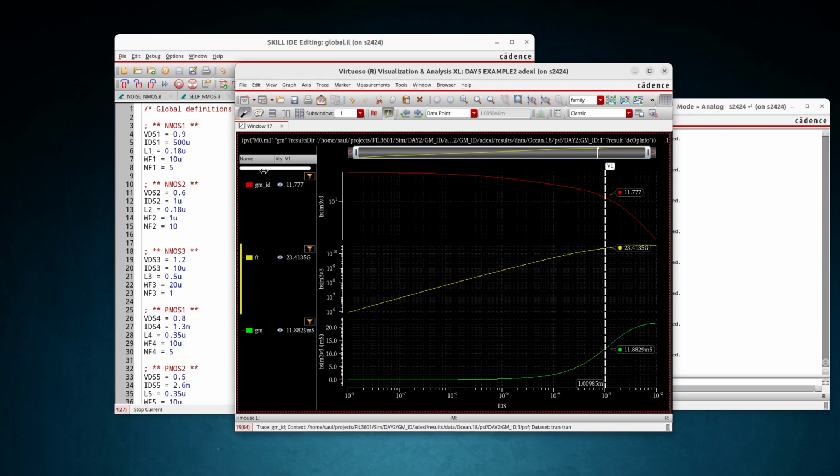for 1 milliamp and for this size of transistor, what we have is that the gm over ID is 11. It is not very high. The frequency performance is actually very good, 23 gigahertz, but the bandwidth of our system is just 1 megahertz, so we have a very large margin. So maybe we can exchange some of this high performance bandwidth, and we have 11 millisiemens. So we can probably plug in these values and see what happens.